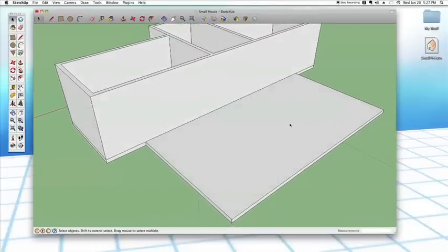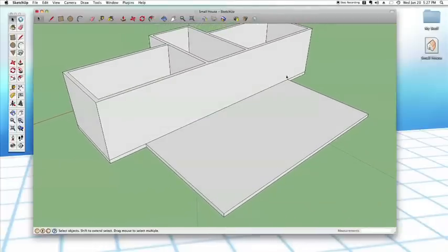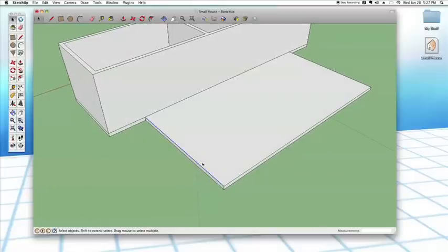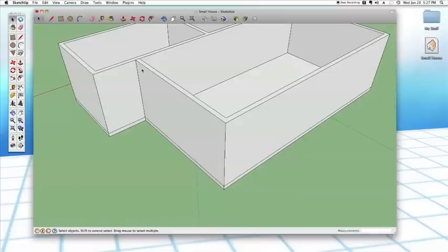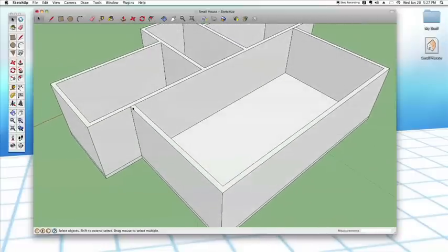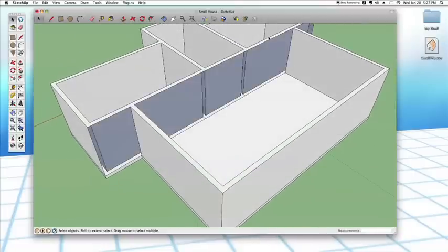Now, what I'm going to do first is add these exterior walls here. So I'm going to do that by selecting the lines that I want. I don't want a wall here, so I'm going to leave that unselected. And then offset these 6 inches in. Pull up a copy for my walls. There we go. Perfect. Just going to select these dividing lines right here.